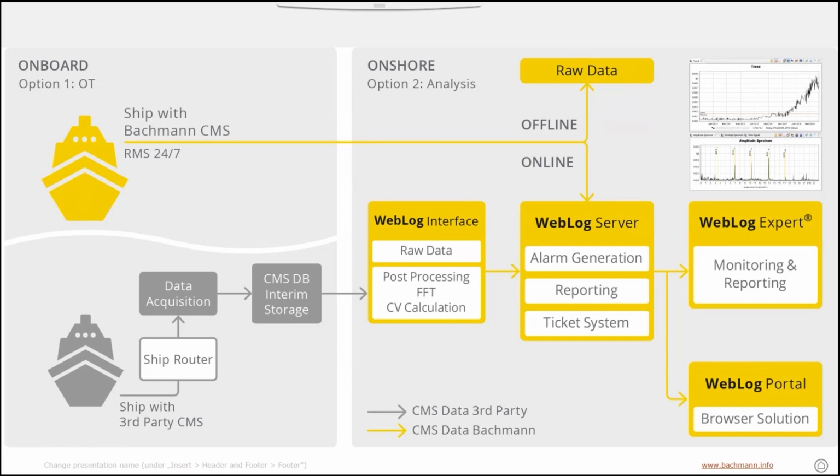So our control system, the controllers from Bachmann, can do a lot of the work near the machine. They're effectively edge devices. They can do all the vibration analysis close to the machine, but probably you don't want too deep an insight coming straight into your control room or your bridge or your engineers on site. On the ship, you want that data available for specialists to look at, but you want something a little more short term to keep you in the position of knowing what your machine's doing and collecting enough data to do more analysis if you need to.